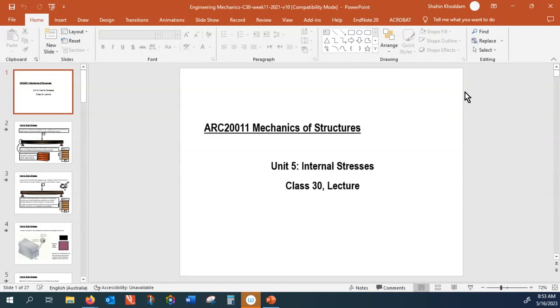As far as the exam is concerned, you want to know the concepts of normal stress and shear stress. Normal stress is when your force is perpendicular to the area. So a stress only makes sense if you are talking about a surface, a section. If you make the section at a different angle, stresses would be different.